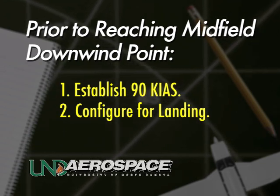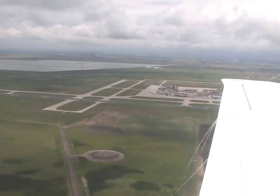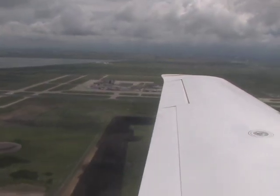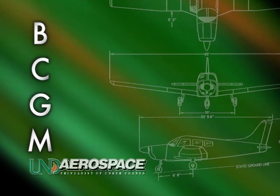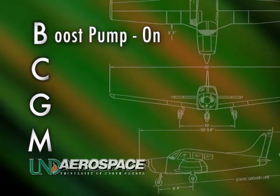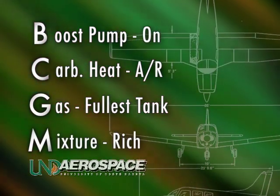Now, what does configuration mean, you ask? Well, specifically, the airplane must be entirely set up for landing except for the introduction of flaps. Configuring can be accomplished using that trusty old Warrior mnemonic, BCGM. Boost pump should be on, carburetor heat as required, gas to the fullest tank, and mixture rich.